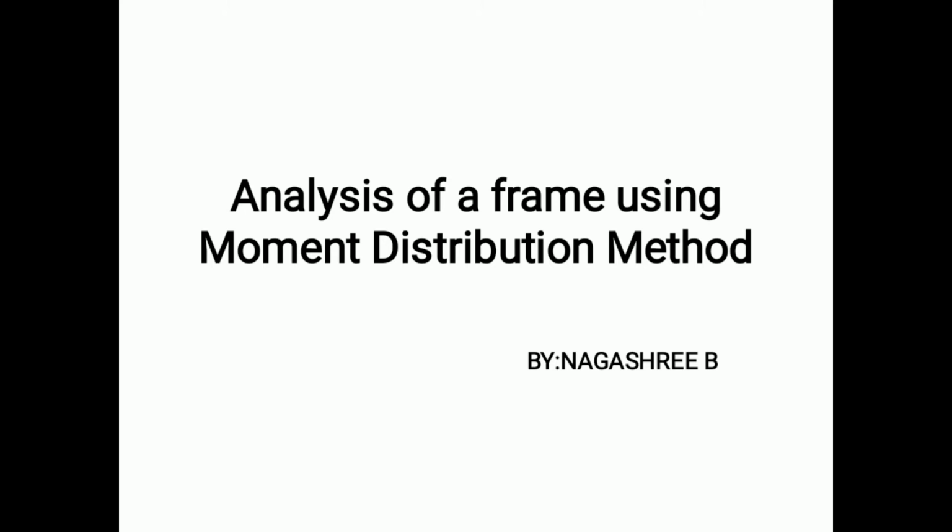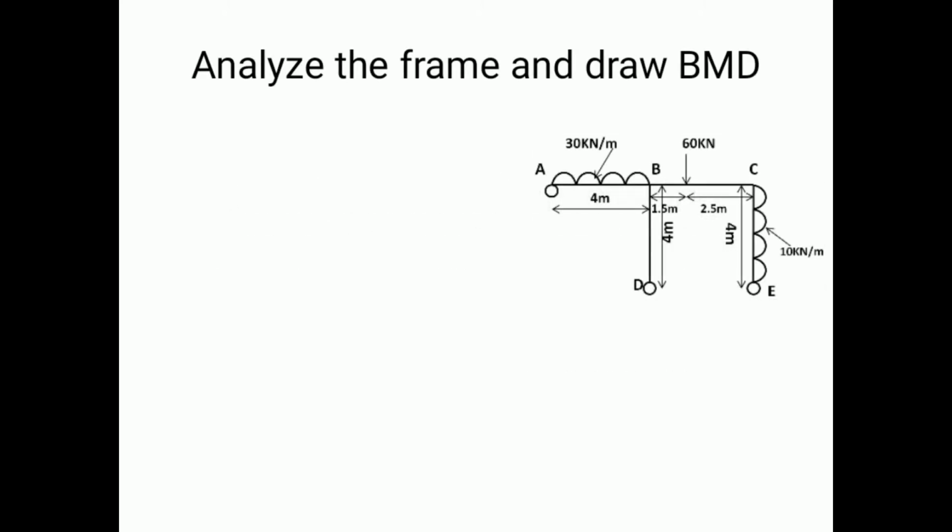Today I'll be discussing how to analyze a frame using the moment distribution method. So I have taken an example numerical of a frame, and we are supposed to analyze it, find out the bending moments, and also draw the bending moment diagram. So here I have taken a typical frame.